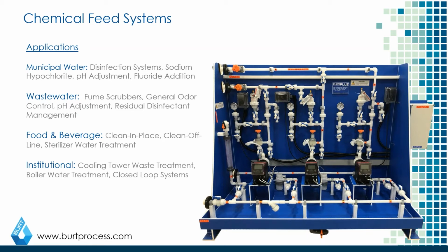Here's a couple more examples of a chemical feed system. Because you're dealing with the nature of a lot of these different chemicals, it becomes very important to make sure that they are properly contained and properly environmentally controlled, because temperature can have a lot of impact on the sensitivity of the chemicals, the piping involved, whether that be PVDF, polypro, or stainless steel, as well as freezing concerns.